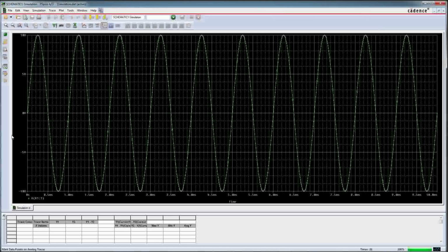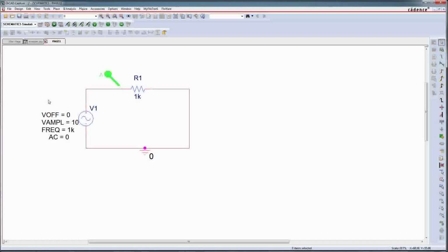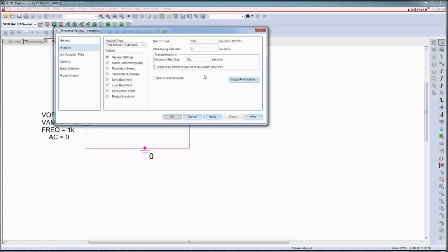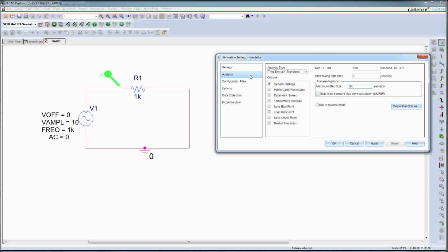It is important that you can see that for this value we need some kind of trade-off. So which value should I use, you could ask yourself? A really small value, a big value? It depends on the frequencies you have in your circuit, because if you use a really small value here, your simulation is going to take time, and if you use a big value here, then you have seen that the resolution is not good enough.